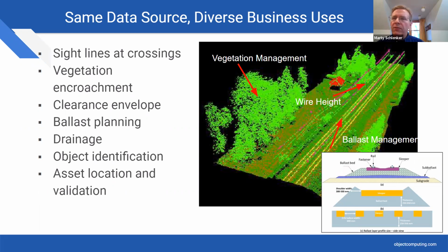But the other thing is you're going to find a lot of common and repetitive objects in the railroad right-of-way. And you need to identify them and make sure that you don't send a crew out to remediate something that has to stay there, such as a signal mast, crossing protection devices, signal bungalows, propane tanks for switch heaters, the dual control switch machines themselves, and other common appurtenances in the railroad right-of-way.